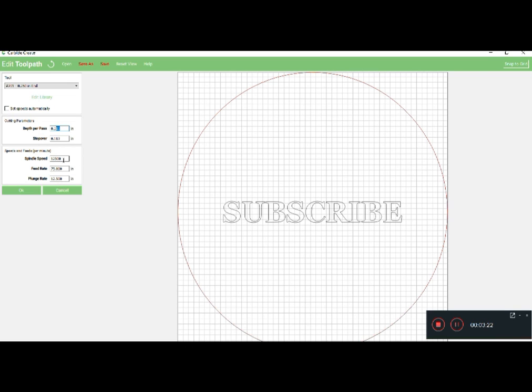But the speed rate, if you go to spindle speed, don't worry about this, because you can't adjust your spindle speed anyway. The feed rate is 75 inches per minute. What's nice about that is that you can actually adjust this, right? You can bring this down to 50. You can bring it down to 20. You can bring it down to whatever you want.